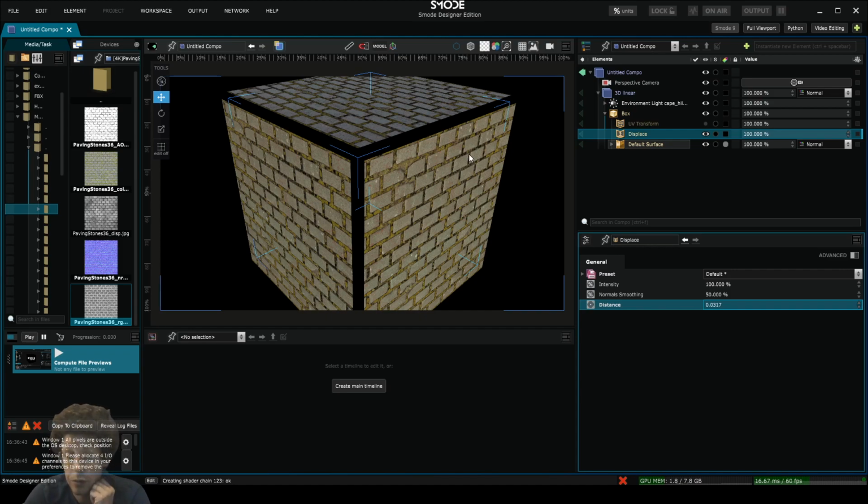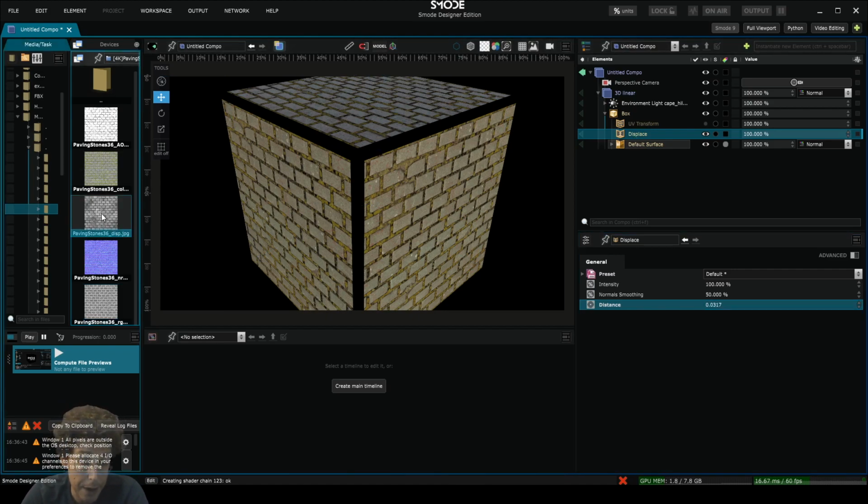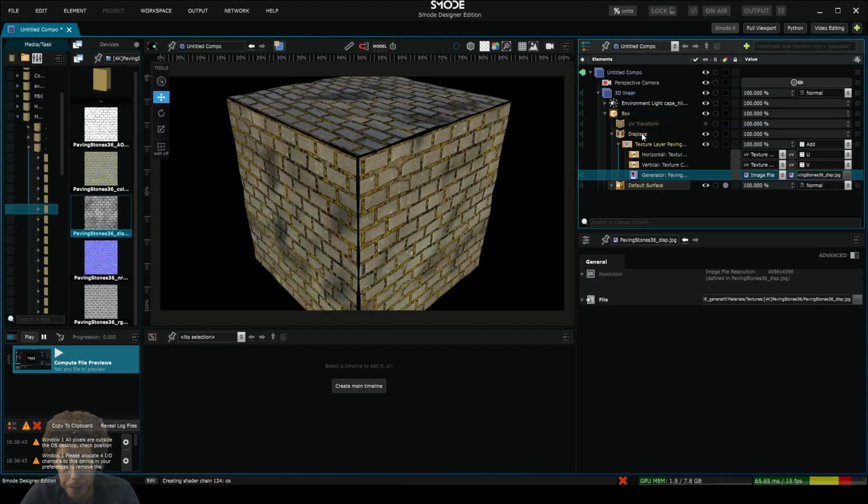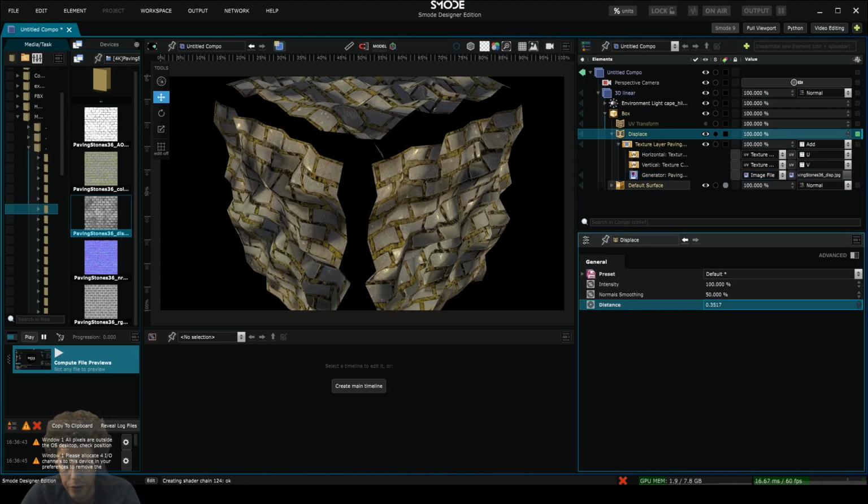So it just displaces the geometry, pushing every point towards the outer edges. And let's create a layer mask on this modifier. To do that efficiently, I will take my displace texture, and this time not use Alt drag and drop, but Control drag and drop. So I press Control, drag and drop on the displace modifier, and it does something, but quite ugly. Let's change the displace value.